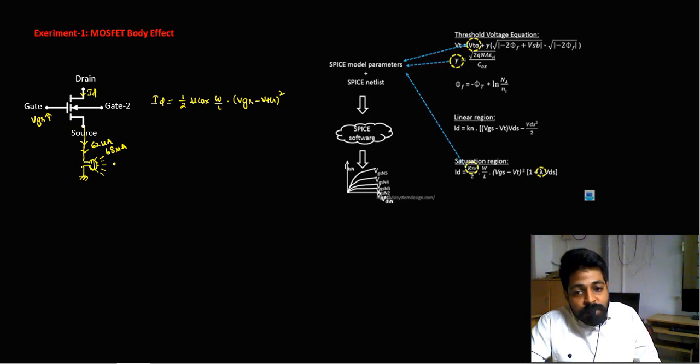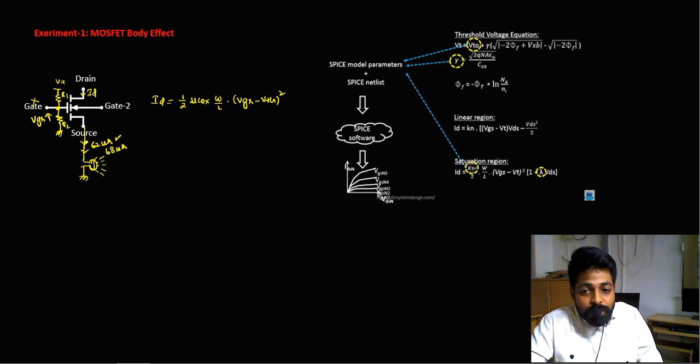But the problem here is that the circuit is given the gate bias voltage through the ladder network. It is VCC, with an R1 network and an R2 network. If this biasing circuit is fixed, the current I am able to get is fixed. The voltage across the gate terminal cannot be changed, so the device can only provide 62 microamperes. The current cannot be changed. Now we have to think, is there any other alternative across the MOSFET where I can increase the current to around 68 micro.